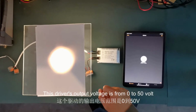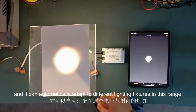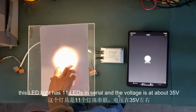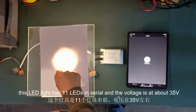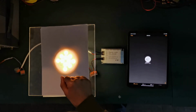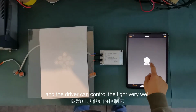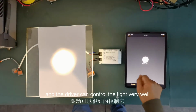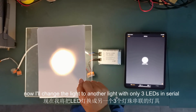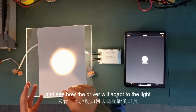This driver output voltage is from 0 to 50 volt, and it can automatically adapt to different lighting fixtures within this range. This LED light has 11 LEDs in serial, and the voltage is about 35 volt, and the driver can control the light very well. Now we will change to another light with only 3 LEDs in serial, and see how the driver will adapt to the light.